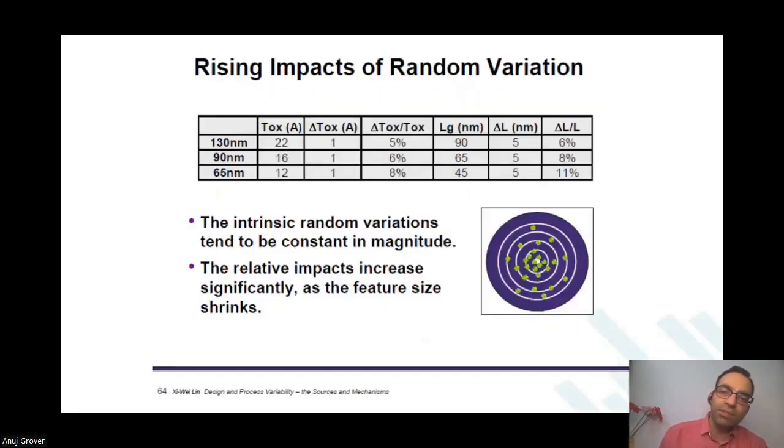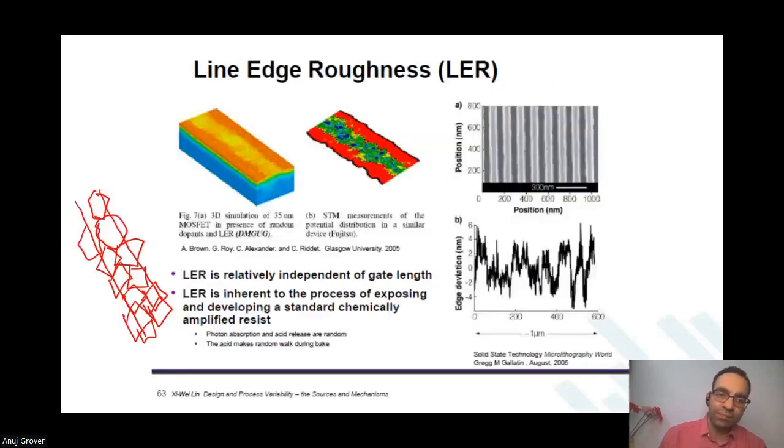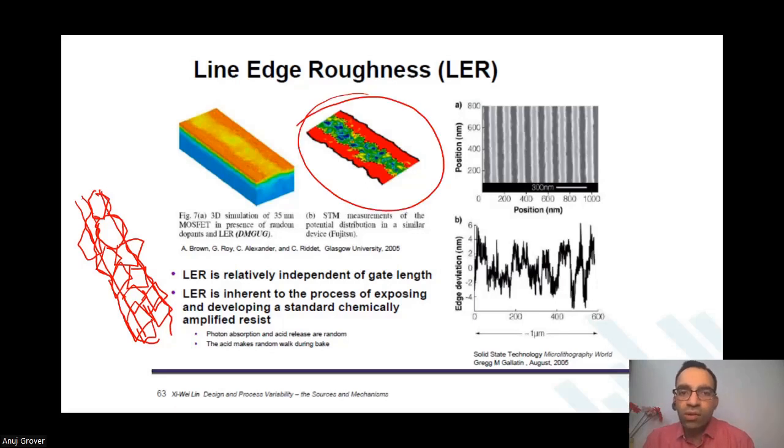At the crystal boundaries, the extent of etch changes. So finally, you may have a polysilicon line. You wanted it to be completely straight and parallel. Finally, you will have a polysilicon line which could be like this. Thicker somewhere, thin somewhere, and so on. You notice in this image, the poly thickness is not constant throughout.